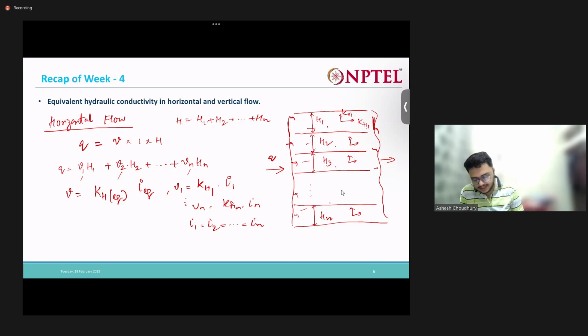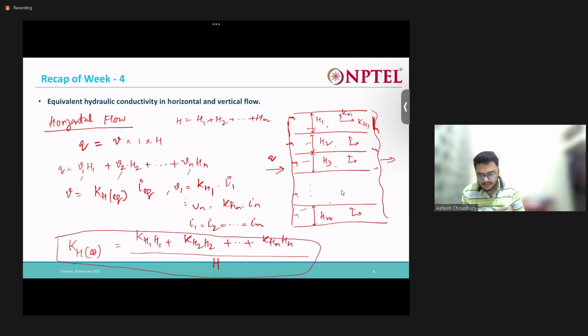So what we can write is finally KH equivalent is nothing but KH1 H1 plus KH2 H2 plus dot dot dot plus KHn Hn, divided by H. So this is my final expression for the equivalent hydraulic conductivity, right?